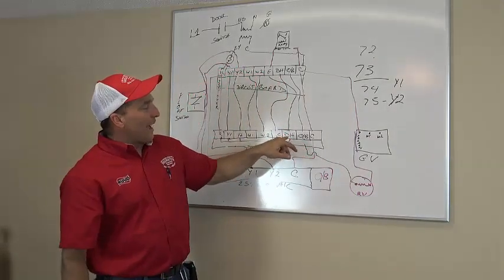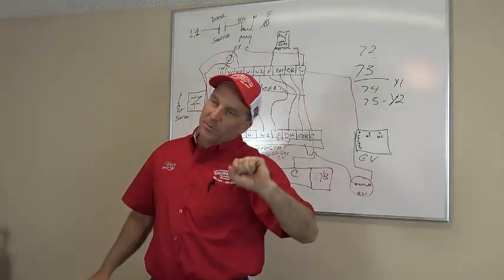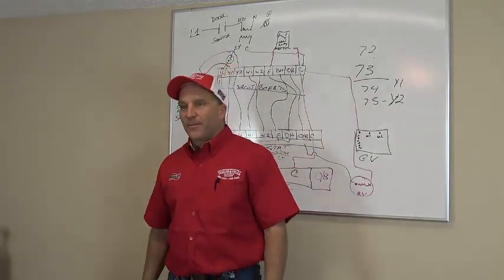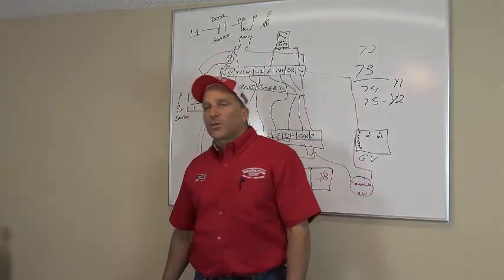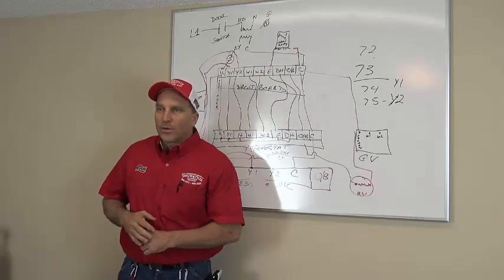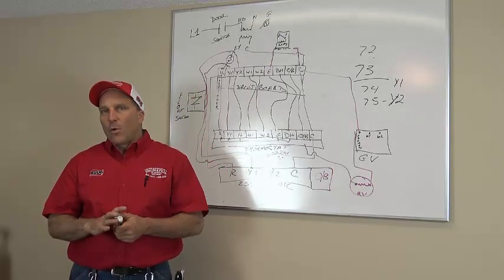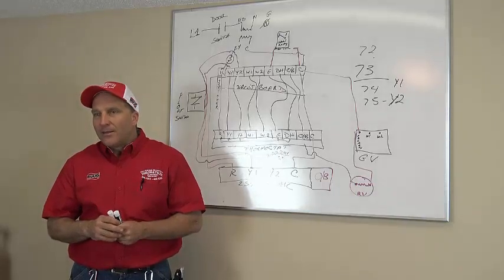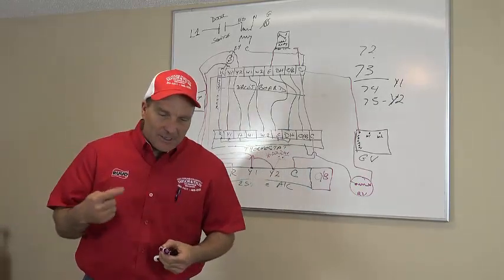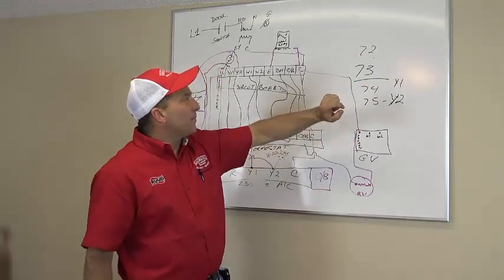Dehumidification. That actually sends voltage to the circuit board, which then on a variable speed system slows the blower speed down about 10, 15, 20%. Okay? If it slows the blower speed down, it makes the coil colder, right? So if the coil gets colder, it removes more humidity out of the air, right? If I remove more humidity out of the air, I dehumidify the home. When I dehumidify the house, the air conditioner continues to run. So here's what happens. Set your thermostat at 72, guys.